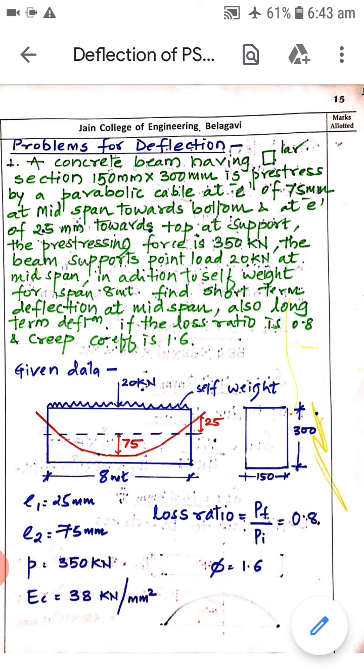A concrete beam having a rectangular section 150 mm by 300 mm is prestressed by a parabolic cable at eccentricity of 75 mm at midspan towards bottom, okay, and at eccentricity of 25 mm towards top at support. So they are given the eccentricity at midspan and eccentricity at support, okay. The prestressing force is 350 kN. The beam supports a point load of 20 kN at midspan in addition to self-weight for a span of 8